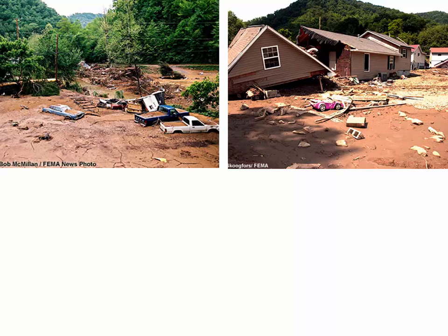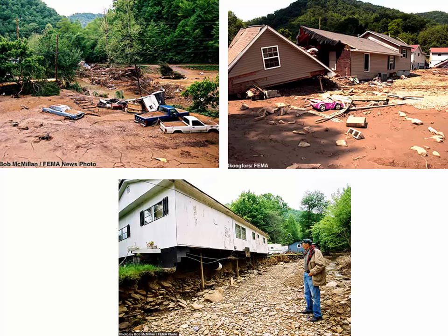That mud wasn't there before the flooding. It got transported because when the water is moving very quickly, it suspends the sediments that normally are settling on the bottom of the channel. And so it's got a bunch of silt and clay and sediments in the water, and then when the water starts slowing down, all those particles settle to the bottom, and then they're just left and they have to be shoveled out. You can see that this guy's foundation has been eroded as the stream just starts getting wider and wider as the water scours the edges of the stream, and now he's wondering if his house is going to start to crack and fall in.